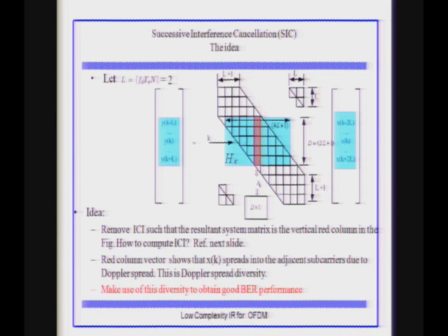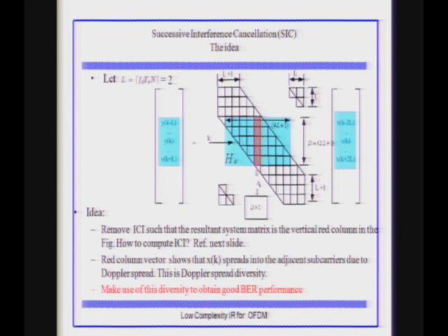We'll see the gains soon, but that is the diversity. I mean, that is the maximum you can get. Whatever coefficients are coming there, that is the best you can get out of the system. And one more thing you can say is once you have higher L, bigger L, these terms get bigger. So you gain more diversity as the Doppler goes up, and we will be seeing that when we look at the results. Since we are cashing in on the diversity, the higher the L, the better our scheme ought to be.